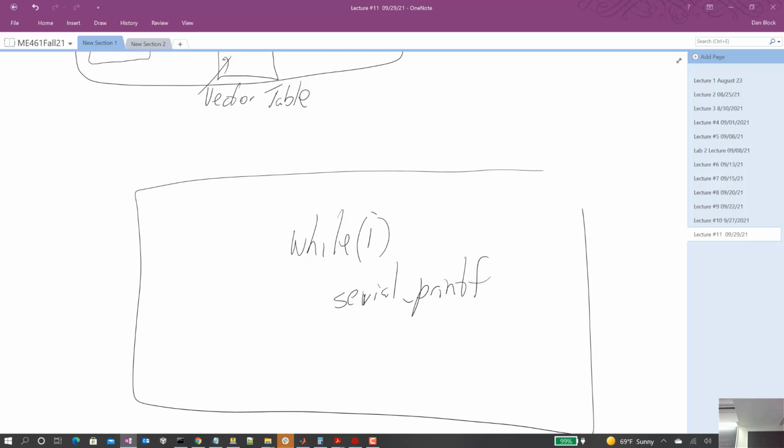Whatever we're doing. Read those values of the results registers, convert it to volts, write the value back out to our digital to analog converter, all that great stuff. Then when it's done, again, because we called the function type interrupt, the C compiler knows to go grab that stuff set up on the stack, put it back to all the registers, and then jump back to where we interrupted the while loop, for example, or whatever got interrupted.